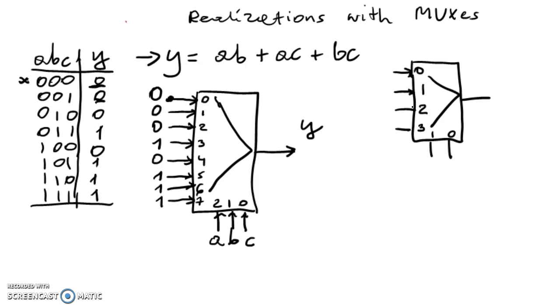And now it is not a straightforward solution, because you have only 4 inputs, and here you've got 8. You even have here 2 out of 3 inputs. So how do you connect this multiplexer to get Y, the same function? Also, this is one of the possible solutions. And the first step, the intermediate step in designing, is to construct a different version of the truth table.